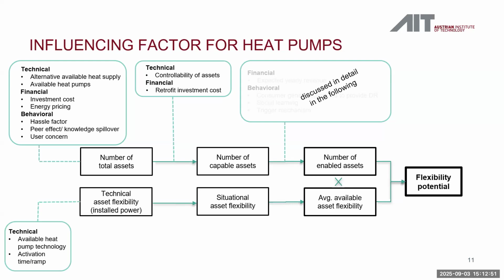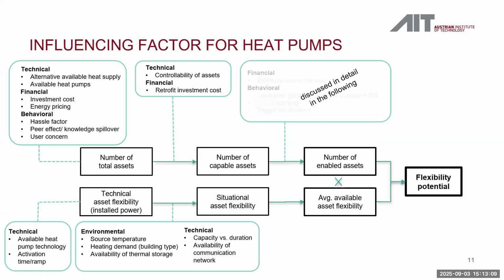Then let's look at the flexibility part. The installed power is dependent on technical factors. That's what kind of heat pump do you have and what are the activation times and ramps. Then where is the heat pump applied? So what is the situation? What is the source temperature, first of all, an environmental factor? The heat pump will need a different power to supply the same amount of heat operated at different source temperatures.